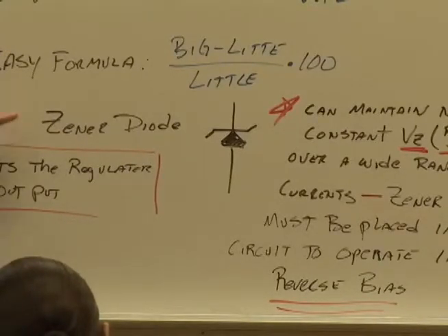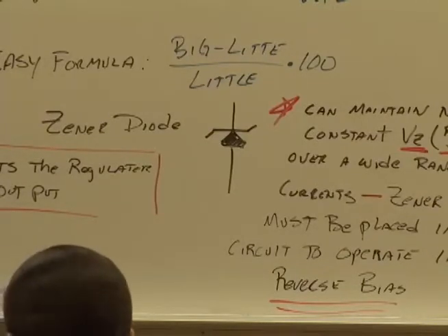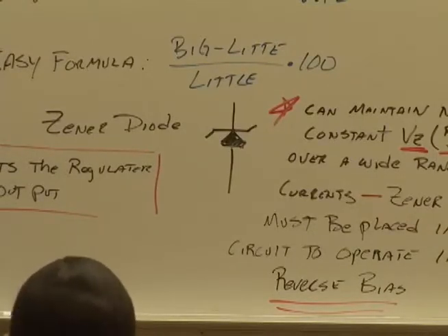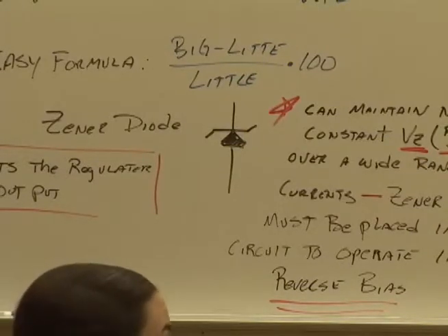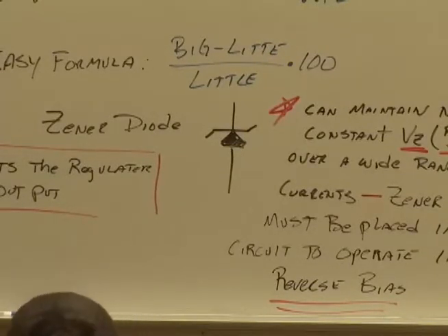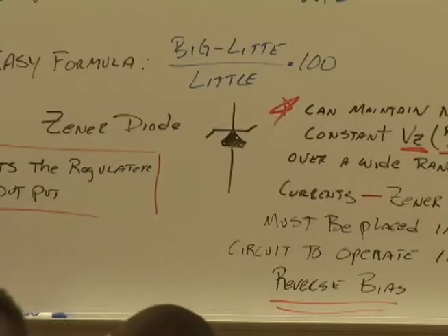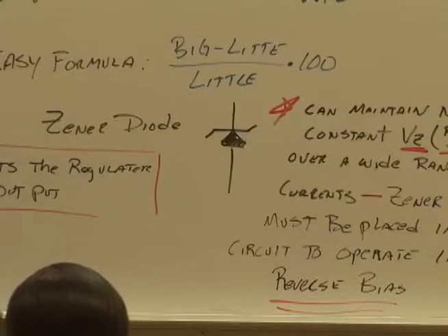The Zener diode in all of these regulators, think about all these regulators we talked about. Isn't there a Zener in every one of them? Even this one? Conceptually there is, right? Because the 3-pin, I drew that imaginary Zener to get you to think of a constant 1.25 volts across the out and adjust pin. So basically, in every one of these, we're dealing with a Zener diode. It sets the regulated output, doesn't it? Not the input voltage.